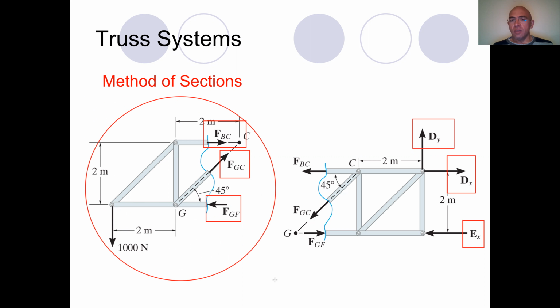Now, I know what the static equilibrium conditions are for a plane problem. In fact, for a plane problem, the sum of the forces in each direction has to be equal to 0, and the moment with respect to any point has to be equal to 0. Now, this basically means that I will write the static equilibrium.